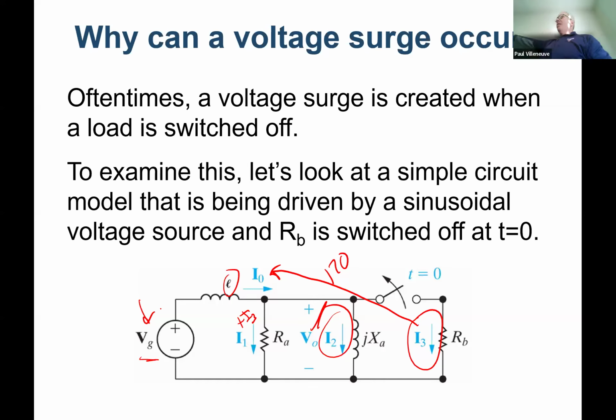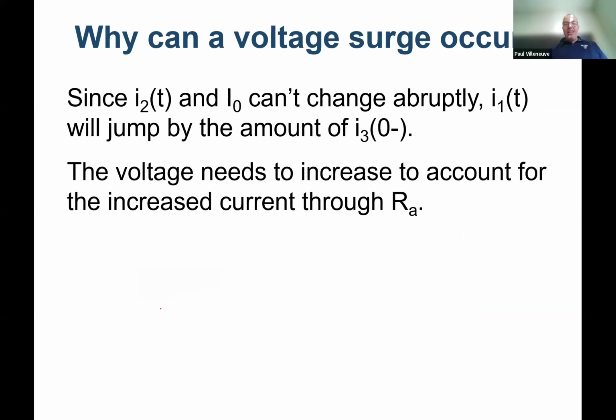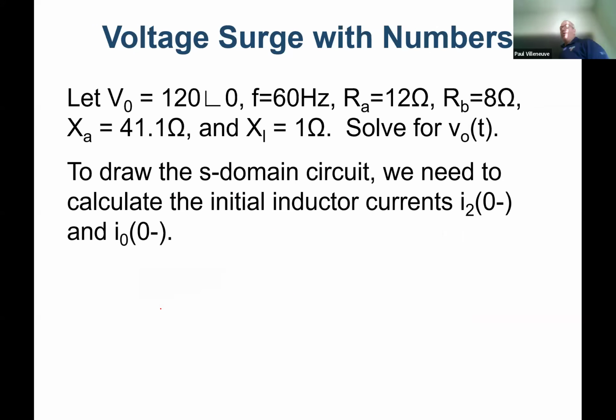So when you're out in the real world, in the utility world, this is how you actually run the system. You set your voltage to your load to be as fixed as possible, and then the utilities and the generators have to monkey with their system as necessary, and they do it all the time, to provide you 120. Because if not, you're waving goodbye to the utility. You're not going to be paying to connect to it. You'll just go to Home Depot and get a portable generator or do something else. So this is way more common. It's always done in the utility world.